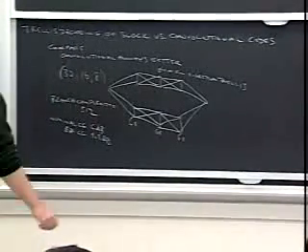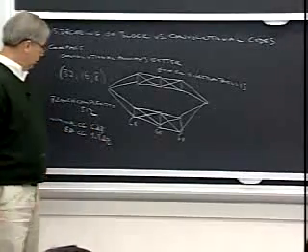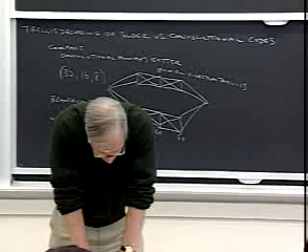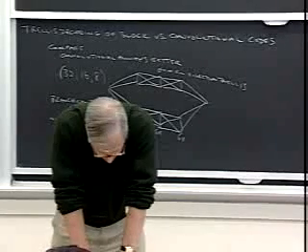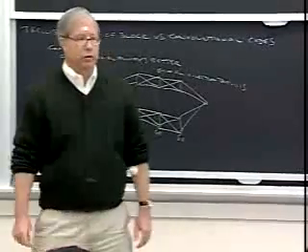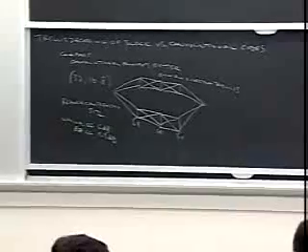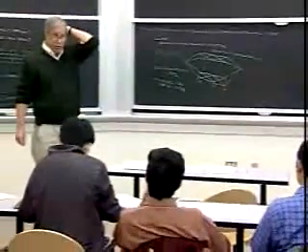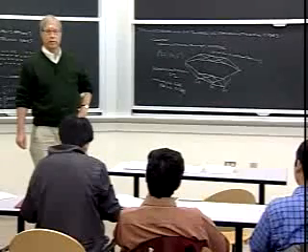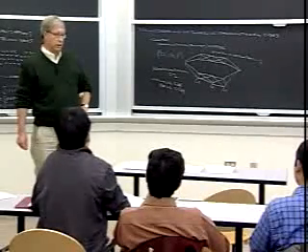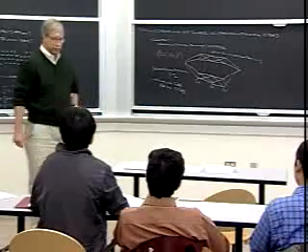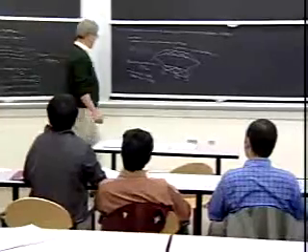Okay, so let's look for a convolutional code of rate 1/2 that has a coding gain of about 5 or 6 dB. And how far do we have to go? We actually only have to go up to a 32-state code, which has an effective coding gain of 5.6 dB. A 64-state code, we can get up to an effective coding gain of about 6 dB. Okay, in fact, the 64-state rate 1/2 convolutional code was a standard for a very long time, first in space communications and then in much more general applications. This was the code that Linkabit Corporation, Jacobs and Viterbi, rode to fame and fortune, made their first pile before they went on to found Qualcomm, where they made a much bigger pile.